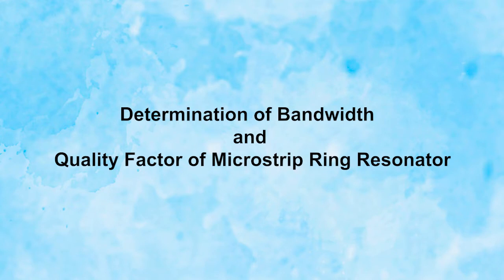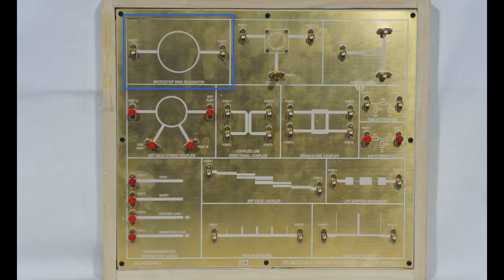Determination of bandwidth and quality factor of a microstrip ring resonator. Microstrip ring resonator is a device that exhibits resonance. It has 50 ohm microstrip feed line and a ring. There is a small gap delta between the ring and each feed line. Resonators are mainly used to select specific frequency from a signal.